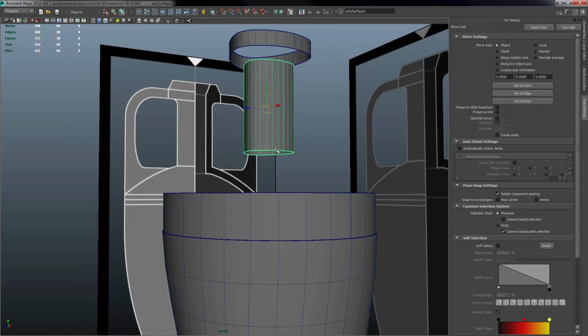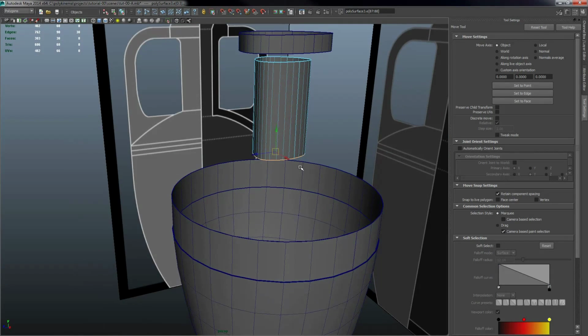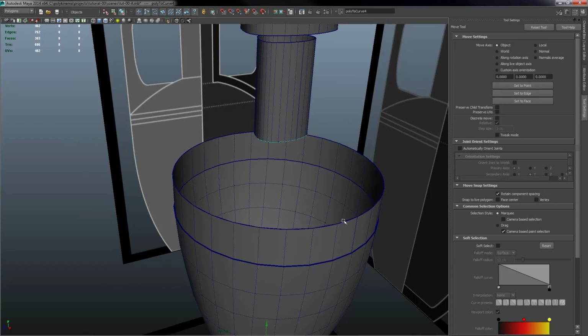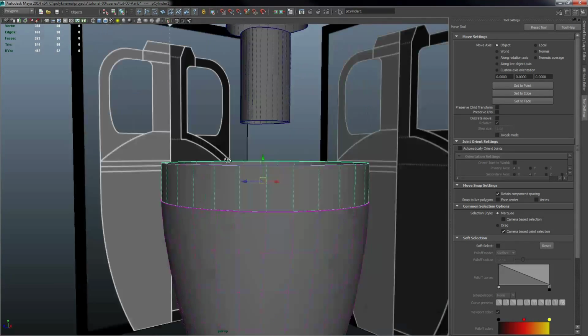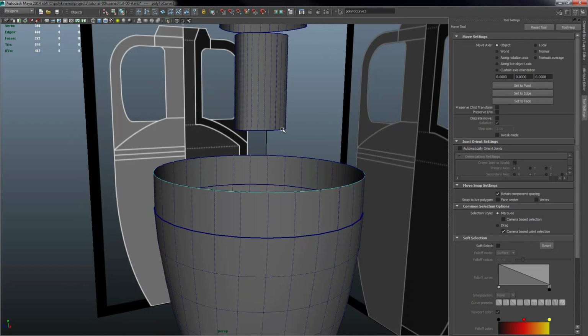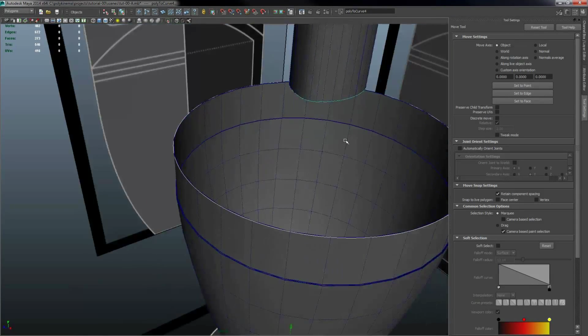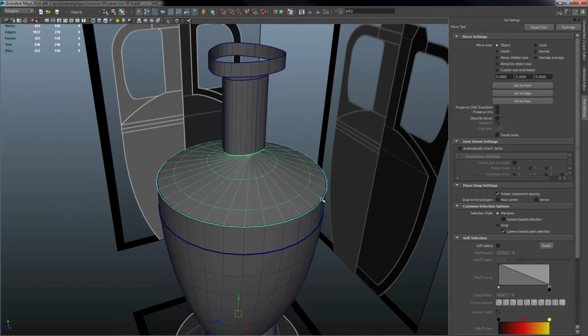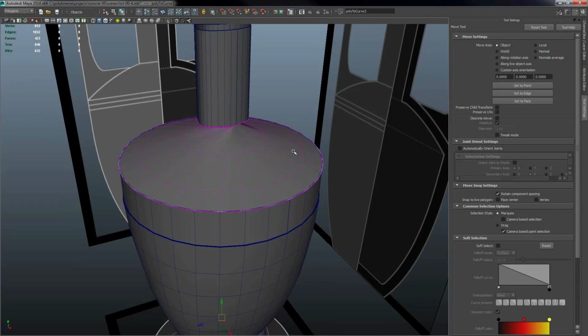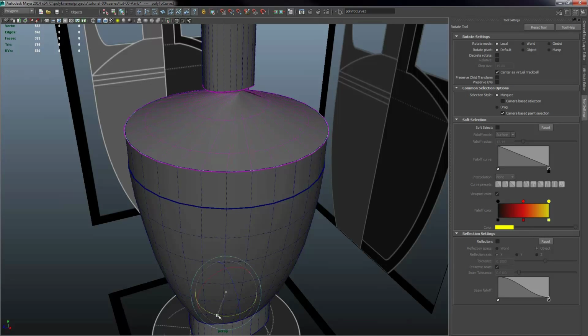Do the same for the bottom of the spout, just hit G. Turn off select polygons so that I can grab those 2 curves and do a loft. And now I want to rotate that back around to make the geometry nice and evenly radiating around.